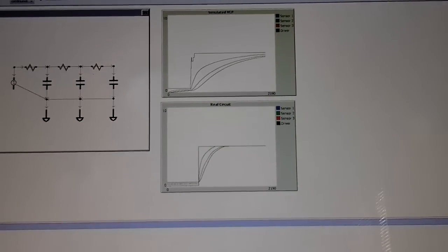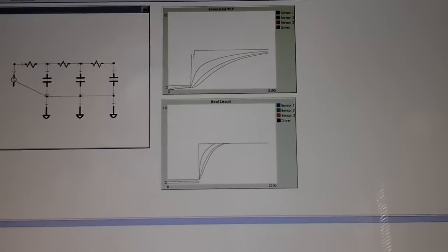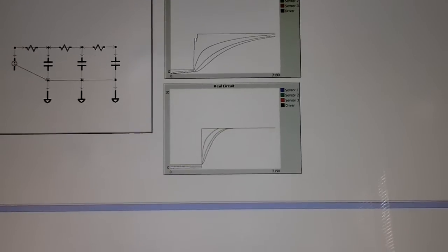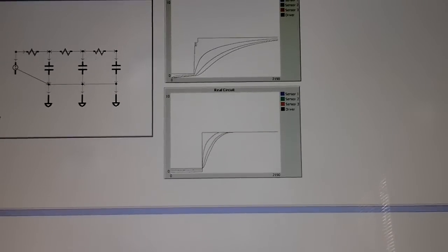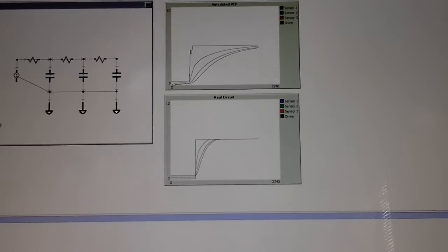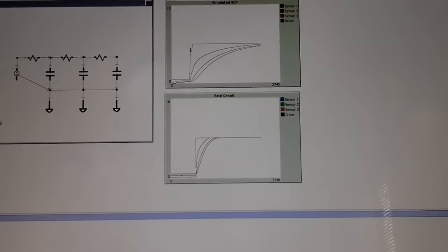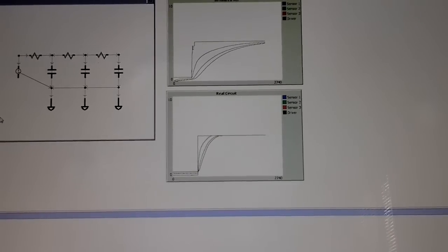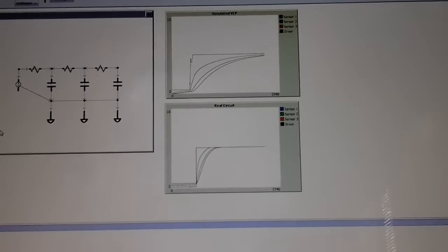The other thing that's happening here is we have a lot of trouble controlling the voltage that the motor drives. So sometimes it's at 6 volts, sometimes it's at 8 volts. So in this case it's kind of high, and so it was driven fast really quick. The other thing is that this was sort of hand-tuned. Well, it wasn't very well hand-tuned. What we did was we just matched the RC values in the simulation to the RC values in the circuit, and then we sort of estimated the time of a tick and then used that as the time constant.